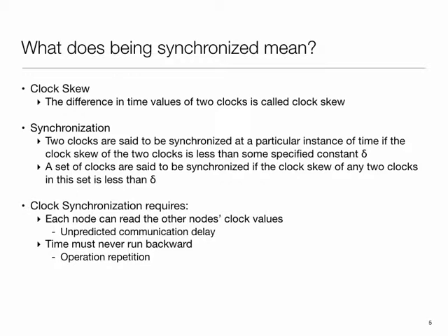Another one is synchronized in frequency. So what that would mean is I send an event and another event which is a certain duration apart. Both of them will measure passage of time and will report the same passage of time, which means that the frequencies are synchronized. But that doesn't mean they need to have the same knowledge of time. They just need to have clock sources whose frequencies are synchronized. So they will report the same difference in count between the two events.